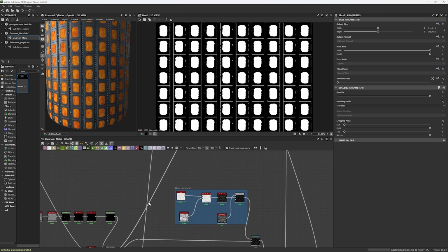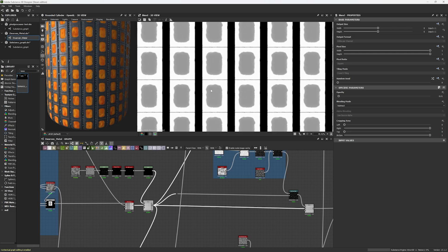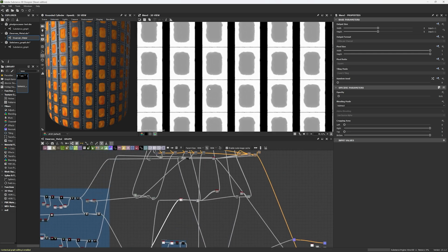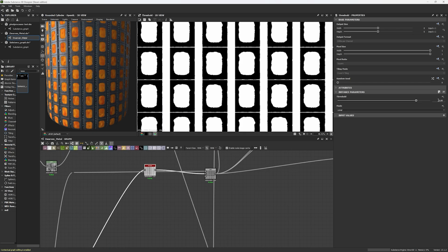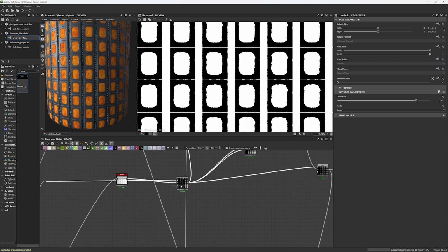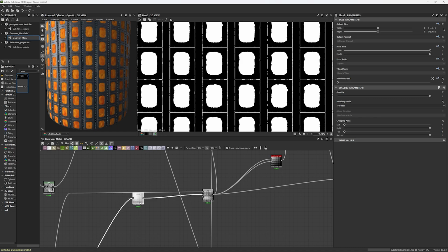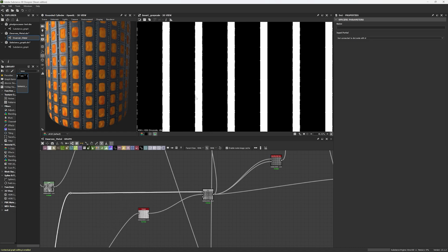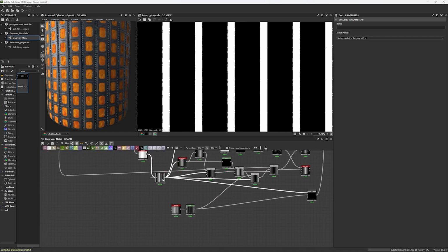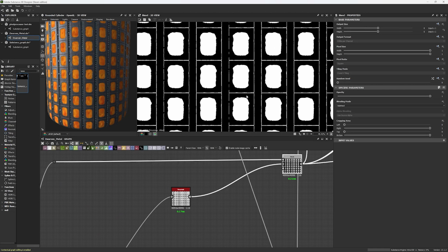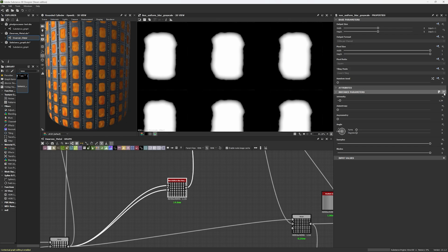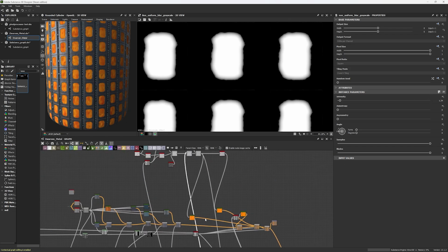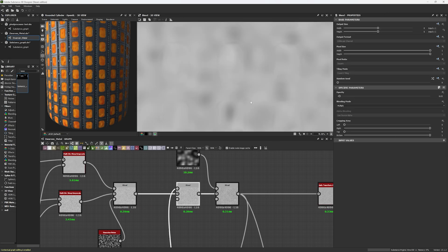So basically we're taking the negative space of these areas. We're taking the space, the circles in here, by using a threshold with a value of 0.85 and set it to lower. Then we're using a blend node that is taking these lines from our previous threshold down here, and it's going to be subtracting just to leave it as this. We're going to use a non-uniform blur with these parameters in order to remove the lines and have only this soft shape, and that's what we're going to be using as a mask to multiply this.